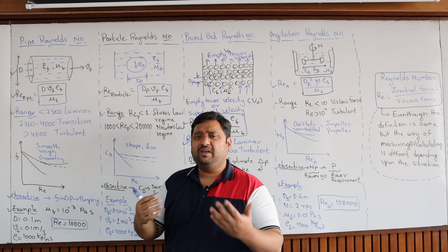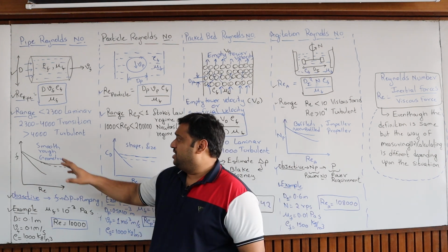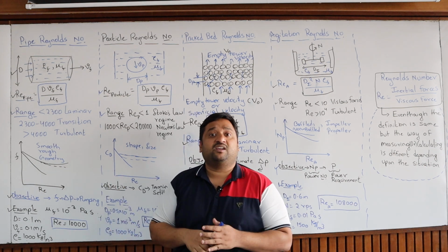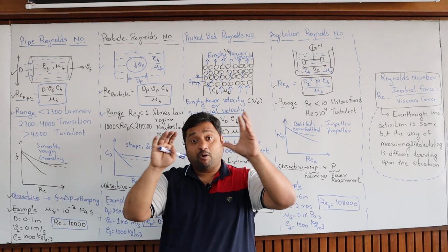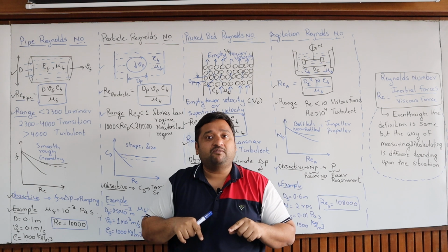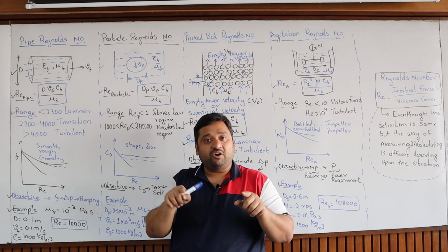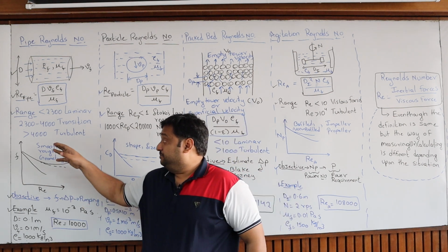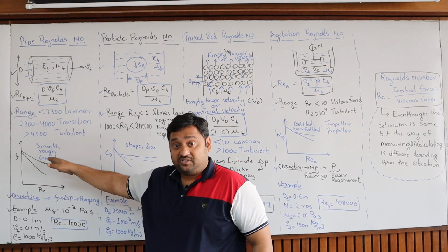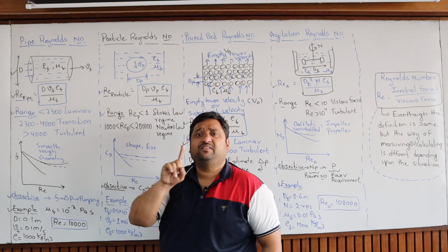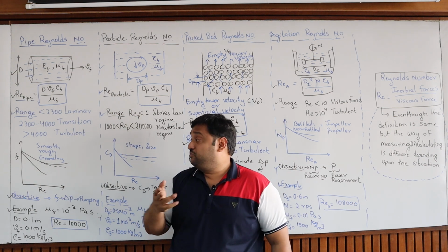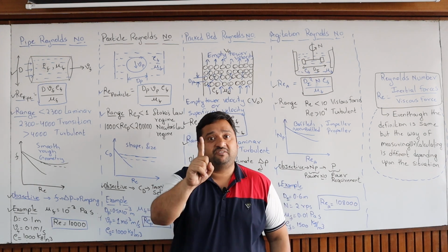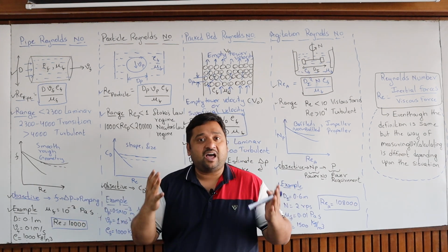it is called turbulent flow. These are what people typically use, because for other situations, like a rough pipe or a different pipe geometry, like a square or rectangular conduit, you get different graphs. This is simply for the pipe. Along with the other situations you have to go for the graph. The objective of the graph is to calculate the friction factor. So there is always a graph.